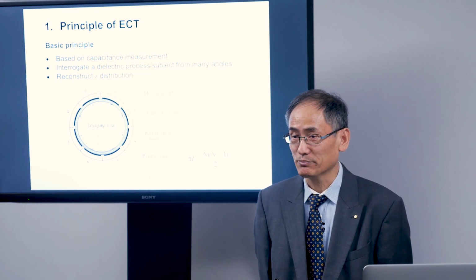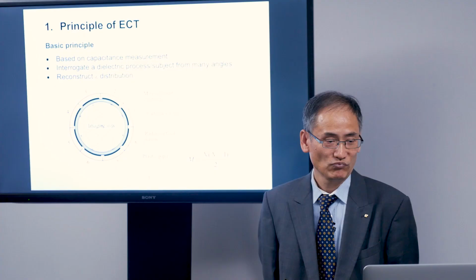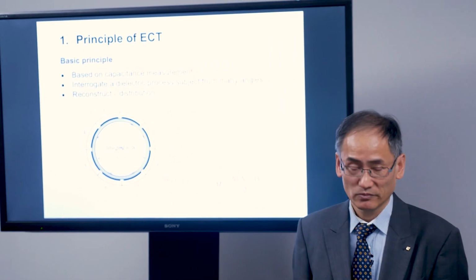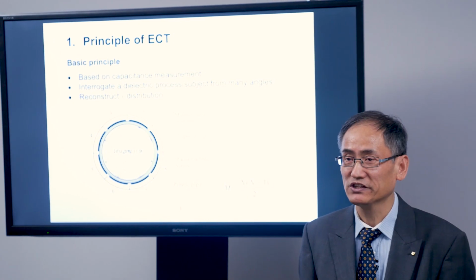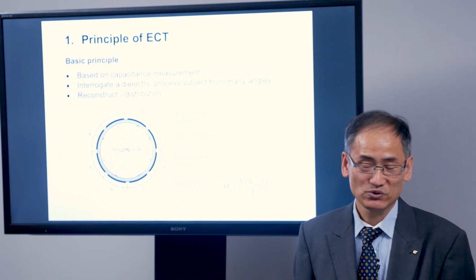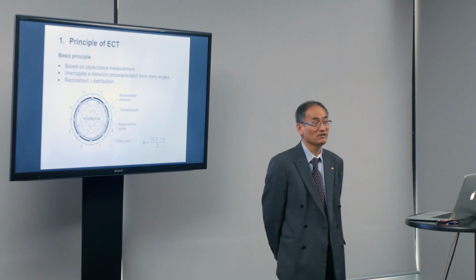The basic principle of ECT I can summarize in 3 bullet points. We talk about capacitance tomography. Obviously, it is based on capacitance measurements. We measure an industrial process or medical subject from many different angles. The objective is to reconstruct permittivity distribution.